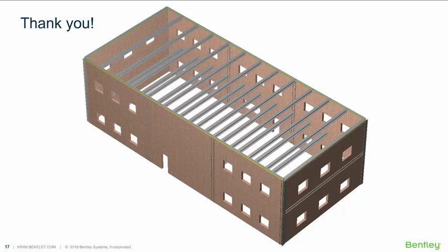So what it says is, I don't know what diaphragm to associate this mass with at this story, so I'm just going to ignore it. What you do instead is you tell RAM Frame, and there's a dialog specifically where this is done, I want to associate the mass at that level with the higher diaphragm. That way, in the seismic calculations, that mass is accounted for, added to the mass that's already there.